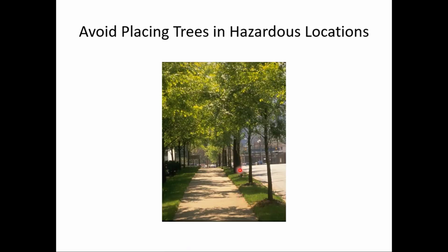And of course, another issue these trees present is not related to roadway departures, but as many of you know, depending on the root system, the tree roots can heave up the sidewalk slabs and create ADA accessibility issues, or can create trip and fall hazards for pedestrians. So that's another concern related to trees close to the roadway where you have sidewalks.